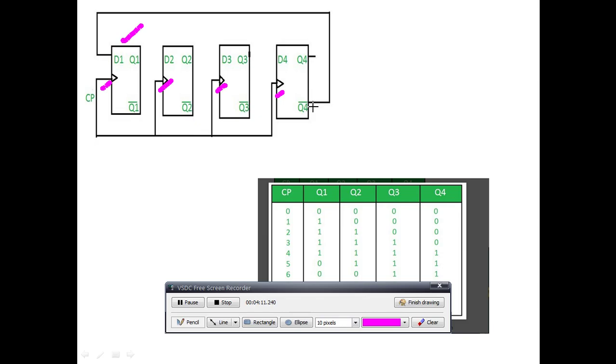But because the complemented output of the fourth flip-flop is taken as input to the first flip-flop, only 8 outputs are generated as shown here. See, only 8 states are available. Only 8 have arrived as used states. What about the remaining 8? They are nothing but unused states.